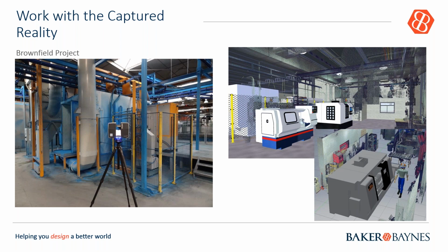If we look at the right hand side of the screen, you'll see that is a recap file that's come in, which allows us to place in our equipment to see where clashes are or if there's any obstructions on the way, so we don't set up our factory with any hazards or obstructions that need to be reworked later on. This is a really nice way of working our brownfield projects, only because we can see if there's any clashes or obstructions beforehand.